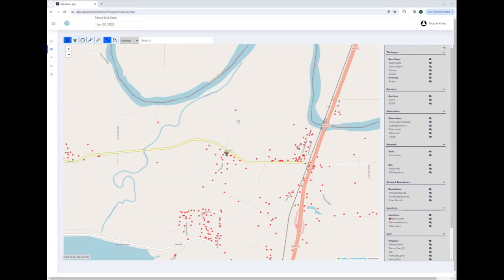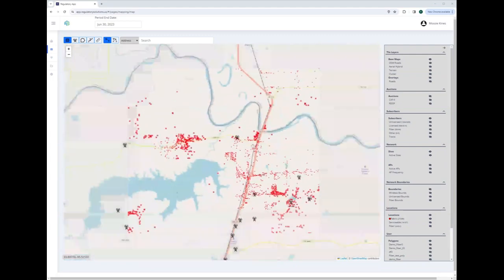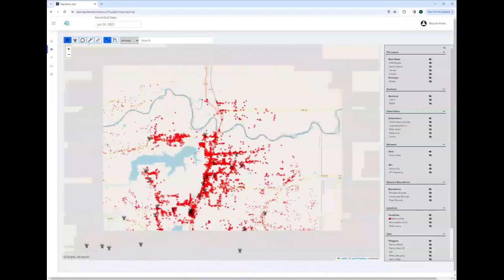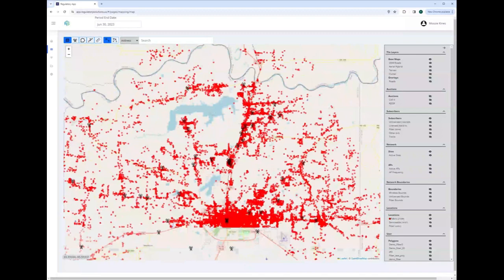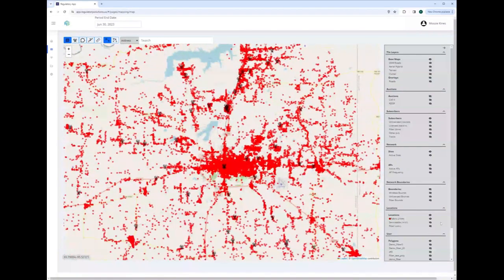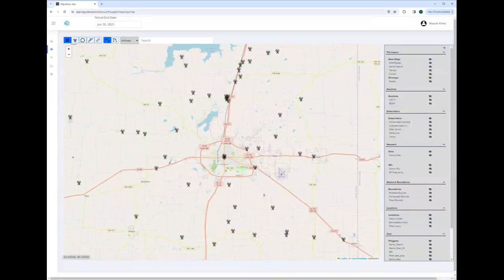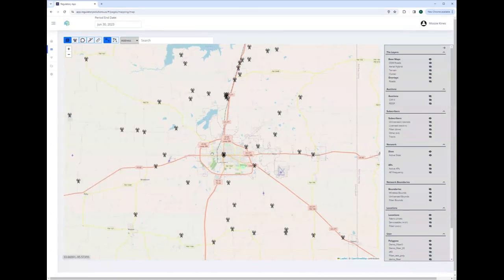So that just about covers most of the features available in the qualification tool that we have, our RF tool. So you can see there are several advantages, just to remind you of our tool versus some of the others. One, we don't use an area mode propagation, which means that we're not trying to go out to every single point on the map and determine what the signal is in, say, since we're using 10-meter clutter and terrain in a 10-meter bin, right? So little 10-meter squares. We're not trying to find signal everywhere.